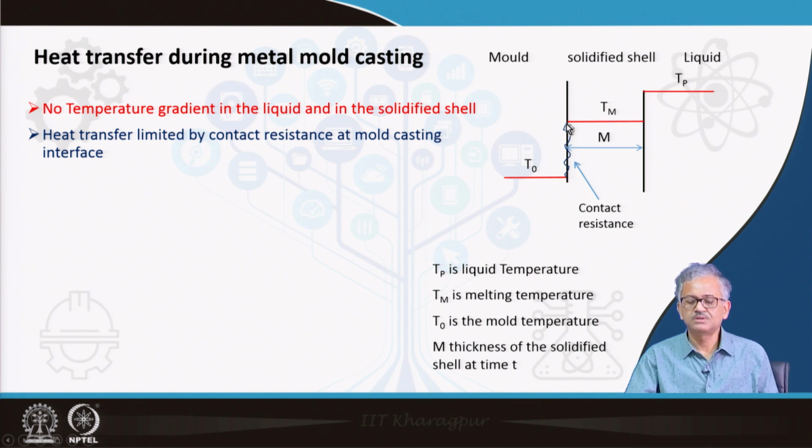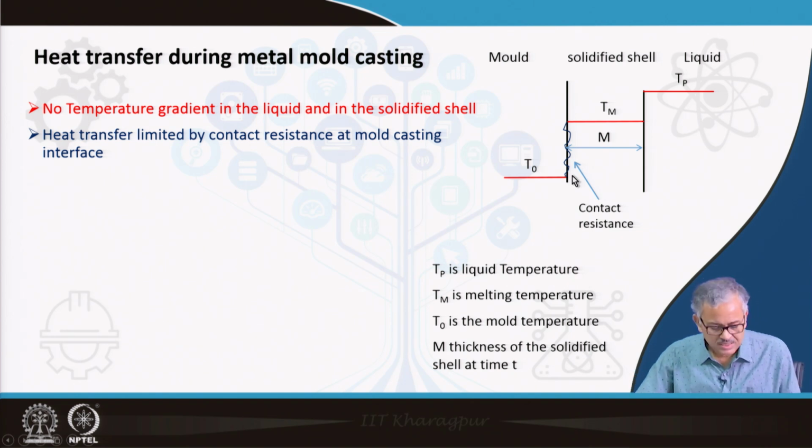Here, if you consider a constant temperature in the solidified shell, you do not consider any resistance to heat transfer, that is, infinite conductivity, which you are considering, but actually it is not. So here this resistance is too high, then this type of assumption may be a little bit justifiable. Okay, because we are assuming that most of the resistance is lying in the interface. So that contact resistance is there.